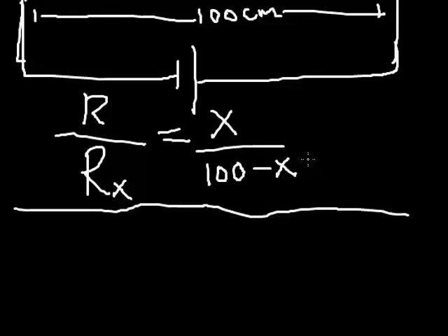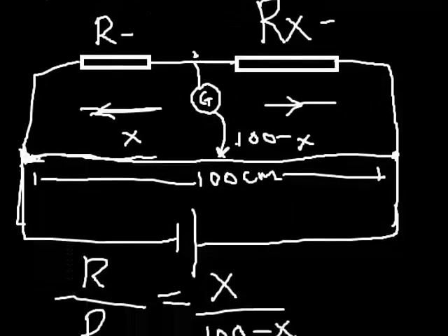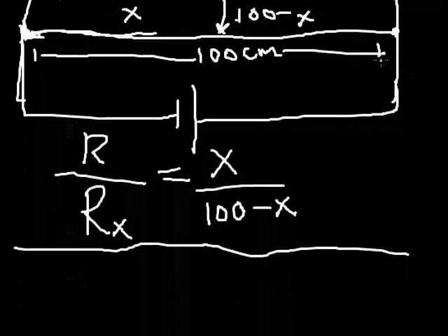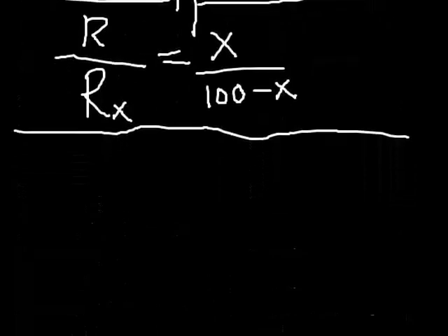So what are Kirchhoff's rules? Kirchhoff actually states two rules. One of the rules is known as the loop rule, Kirchhoff's loop rule, or the voltage rule. What does it state? Kirchhoff's loop or voltage rule states that the algebraic sum of voltages around a loop is equal to 0. So the sum of all the voltages around a loop is equal to 0. Now the question is, what is a loop? A loop is simply a closed path that current travels. For example, this is a loop.